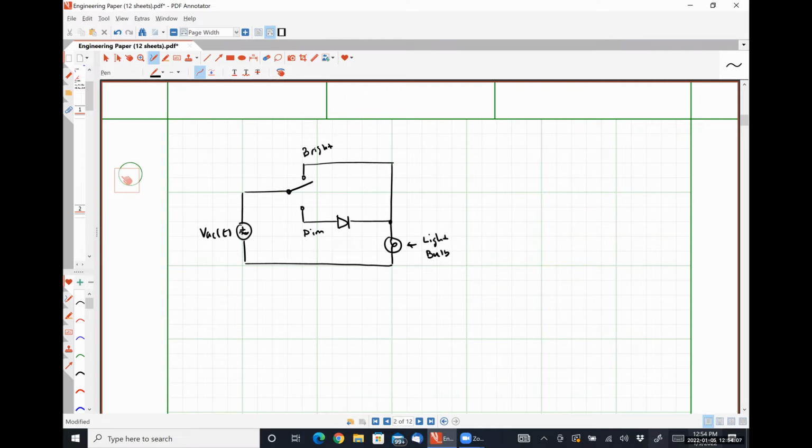Unfortunately, that's really one of the only reasonable applications for a half-wave rectifier. You can't use it to power electronics or anything complicated that requires a good amount of DC biasing, because the variation in the output voltage is so large, we can't actually get a good quiescent operating point. So we need to use it for something that responds very slowly.